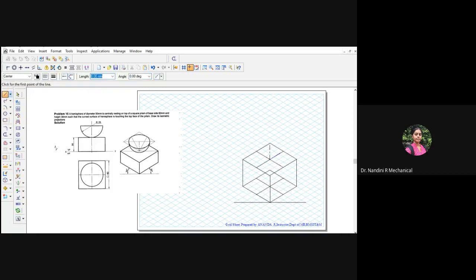So this is the center. This is half and half unit divided. So from here 2.5, from here 2.5, right? Let this be a normal construction line of very less thickness. I'm using line, you use scale and pencil. So from here I will just count 2.5 units. Similarly, back, that is over.